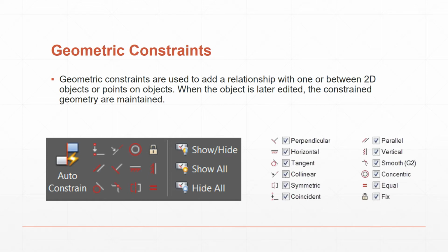Okay, so all the geometric constraints deal with how that line interacts with something else. So if I wanted that line not to move, for example, I can use the little lock button there and fix it. And then that just locks it down in place and says, okay, this line, well, not the whole line, the point on the line is not going to move. It could be fixed. Or I could select the whole object and lock that if I want to. And in the lecture demos, we're going to go over this and we're going to actually see how to do some of these things. And it's going to be quite easy.